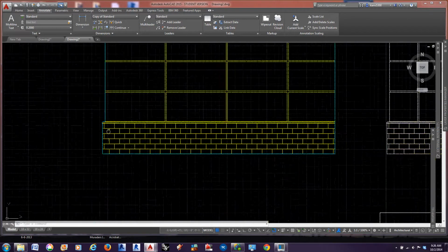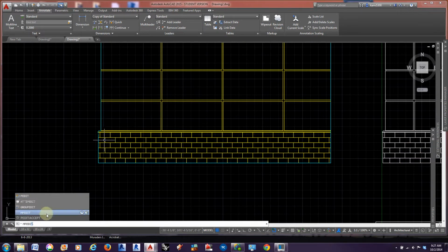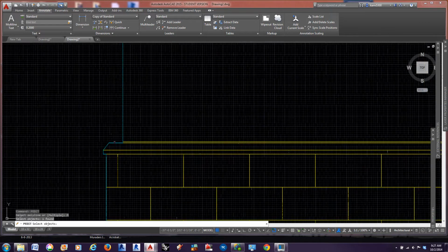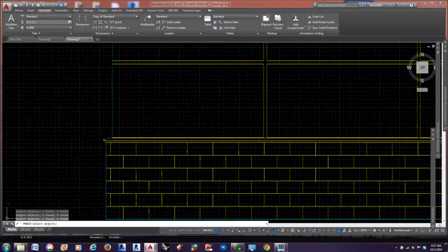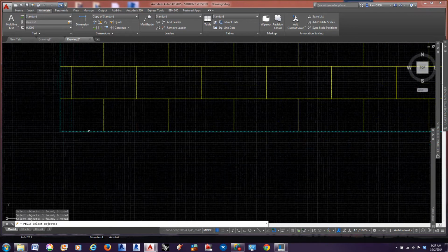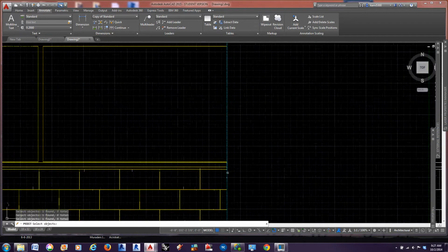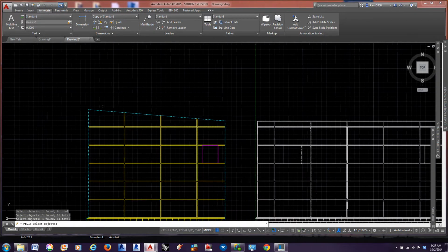will leave a little connection point to the rest of the material. So we're going to go ahead and do a poly PEDIT, which is creating a polyline basically. We want to use the multiple button, and we're just going to go around and select all of our exterior lines. And then hit enter.